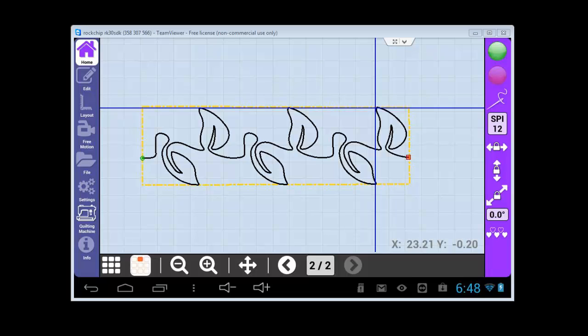You got to run, but I think really I'll just say briefly how that's probably going to work. You'll just need to set pattern boxes, one for the corner and one for the border, and we're probably going to end up using that move start point quite a bit. So what we'll do is we'll stitch out the pattern, the corner block, okay, and then we're going to grab that pattern and move the pattern by its start point, the border pattern. I mean, move the start point to line up with the end point.